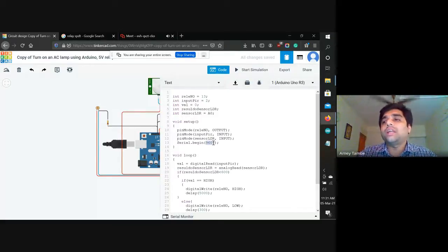Generally when we are using Arduino or any kind of development board, we use a baud rate of 9600, where we don't have any WLAN or wireless sensor attached to it. Once we attach a wireless sensor, we give a different baud rate for that sensor. Depending upon that ratio, the frequency is going to match and the output is going to be printed. So here Serial.begin 9600 is for printing your output, opening up my serial monitor.